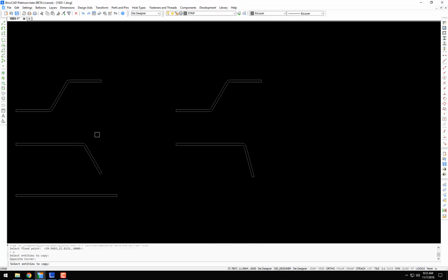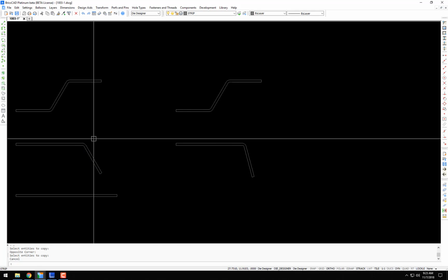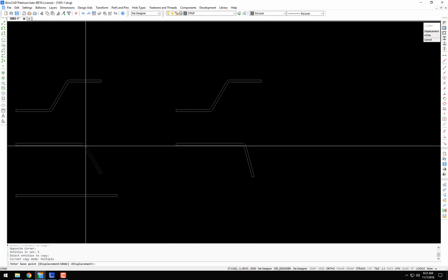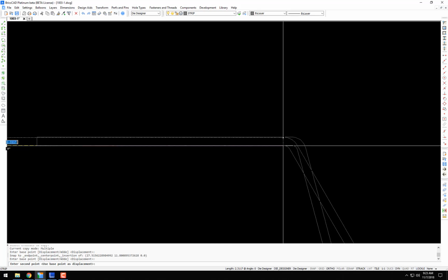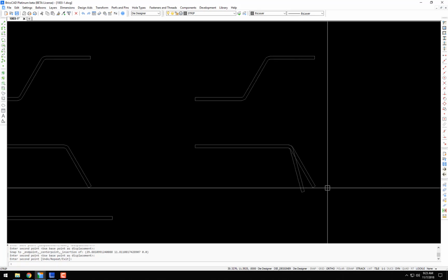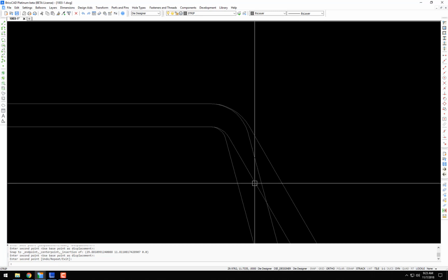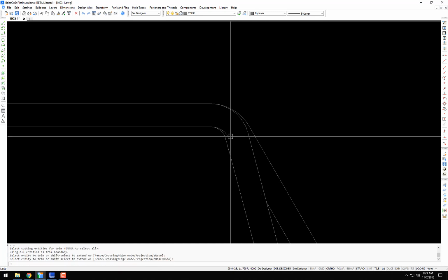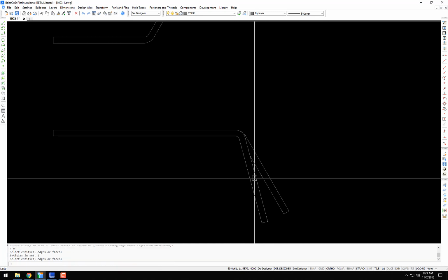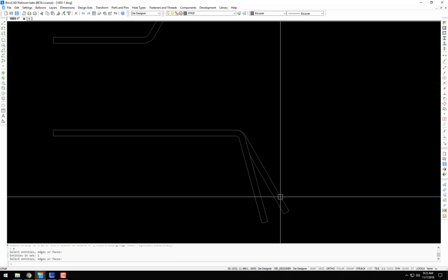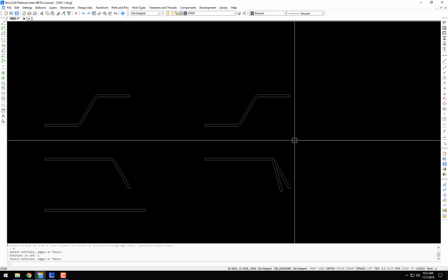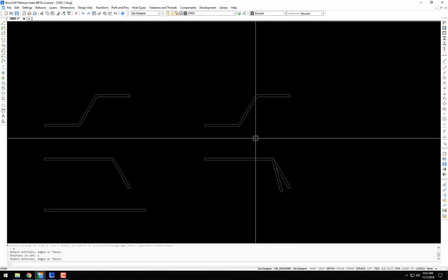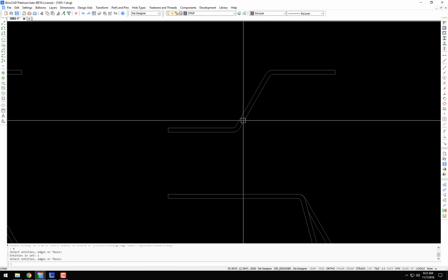When I would draw this in with the formers and all that into a cross section, I would normally bring back our form with the springback, so you could see the springback coming into it. Maybe do a little cleanup. So this is what we're forming it at, and this is what we're anticipating it to come back to, which would be print dimensions.